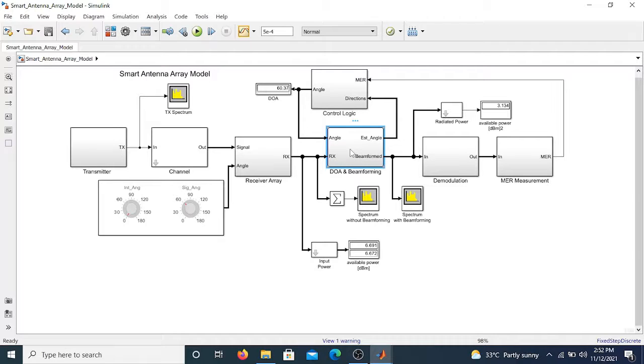The reason for the fixed number of antenna elements is that with MATLAB, specifically in Simulink, during the course of my research, I discovered that with the S parameters, or the number of ports, simply denoted as the number of antenna elements, it's practically impossible to simulate more than 8 antenna elements with noise in the system.